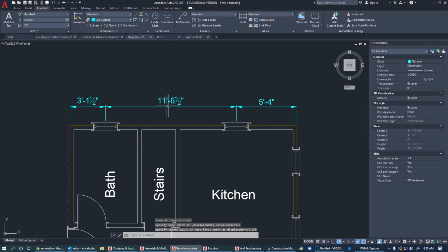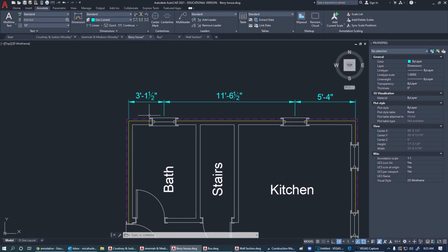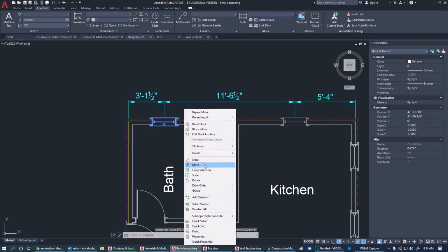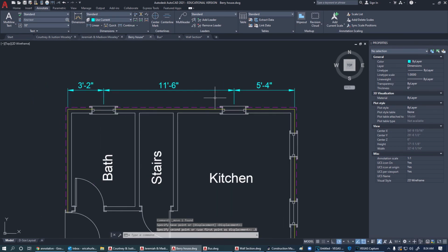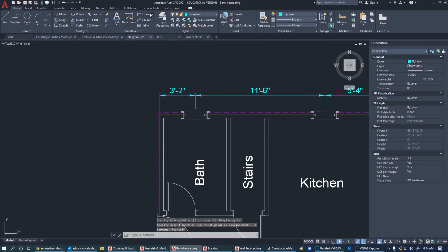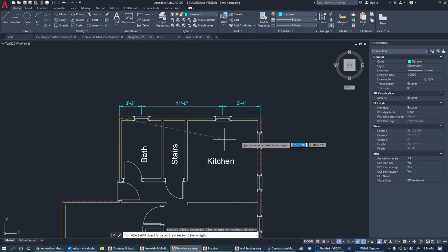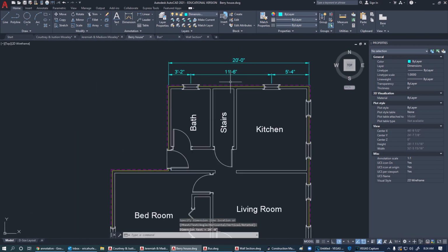Okay, so now I've got some nice things going on here. I'm actually going to do this even more. Make it really simple on the contractor, and I'm going to move this 1/2 inch. That way, there are fewer mistakes, much better. All right, so go back up to my linear. I've got my windows. My windows go on the outside, and then I have an overall, but I also have an offset here. So I'm going to click on my offset.